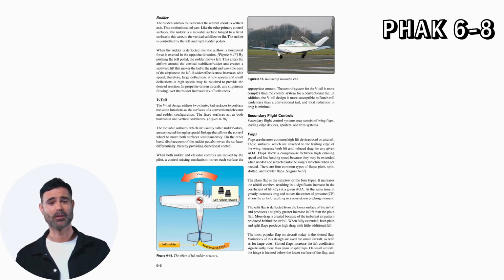There are four common types of flaps: plain, split, slotted, and Fowler flaps. The plain flap is the simplest of the four types. It increases the airfoil camber, resulting in a significant increase in the coefficient of lift, CL, at a given AOA. At the same time, it greatly increases drag and moves the center of pressure, CP, aft on the airfoil, resulting in a nose-down pitching moment.